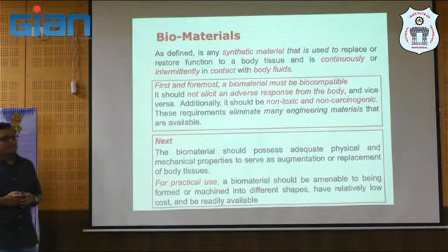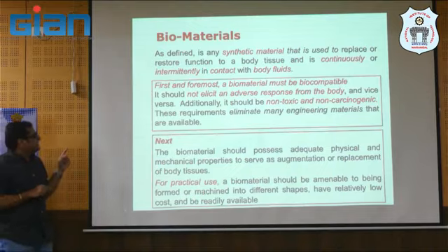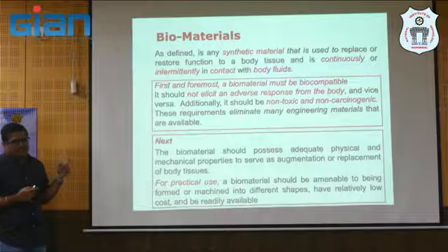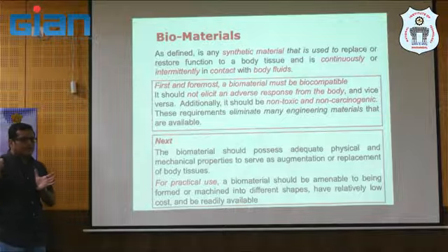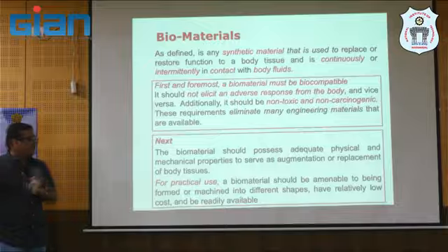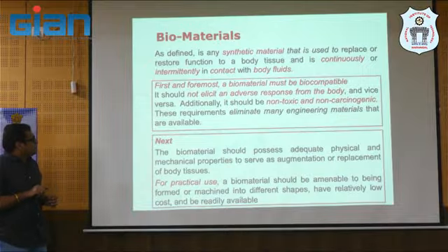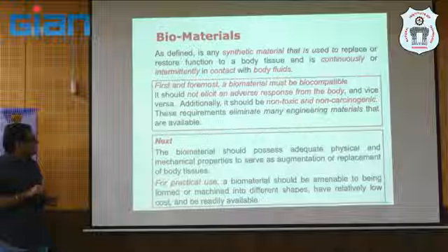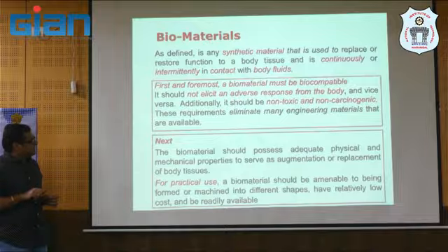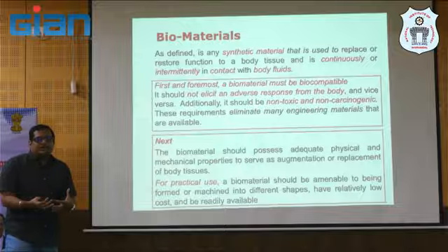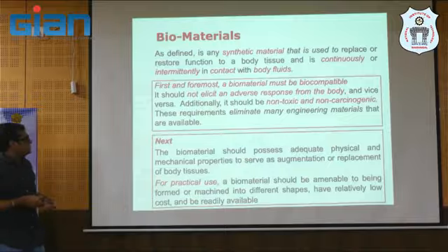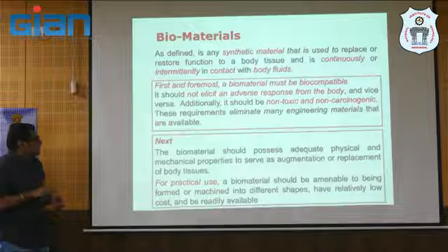Not all engineering materials are qualified. Why? Because it may be continuously or intermittently in contact with body fluid. And you are trying to replace or restore a particular function of a particular body part or tissue, whatever it is. First and foremost, it should be a biocompatible material. What is biocompatibility? It should not elicit any kind of adverse response from the body or vice versa. Once you put this kind of biomaterial inside the body, it should not create any toxic environment in your body. So it should be non-toxic and non-carcinogenic.